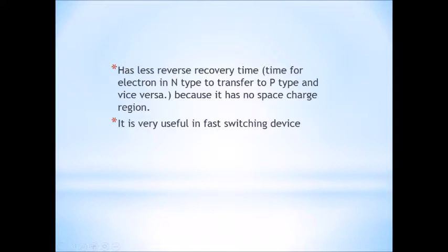After that, Schottky diode also has a low turn-on voltage. When sufficient voltage is applied to the Schottky diode, current starts flowing in the forward direction. Because of this current flow, a small voltage loss occurs across the terminals of the Schottky diode. This voltage loss is known as voltage drop. For example, silicon diode has a voltage drop from 0.6 to 0.7, while Schottky diode only has a drop from 0.2 to 0.3. Therefore, the Schottky diode consumes less voltage to turn on.